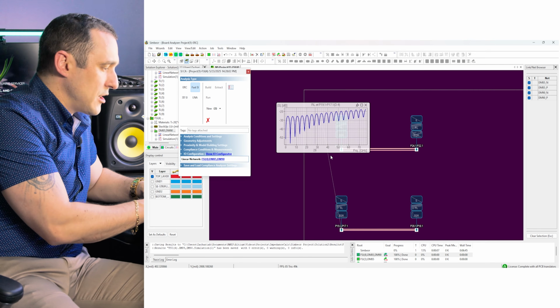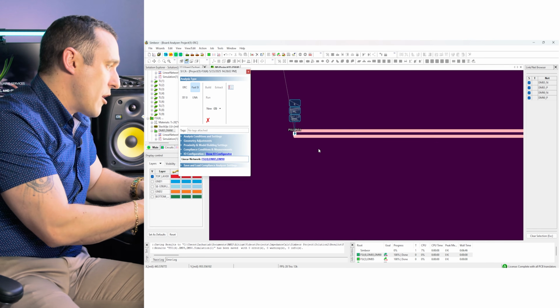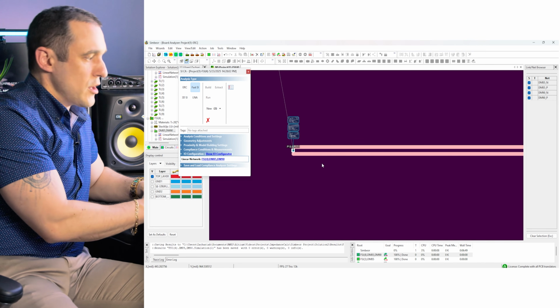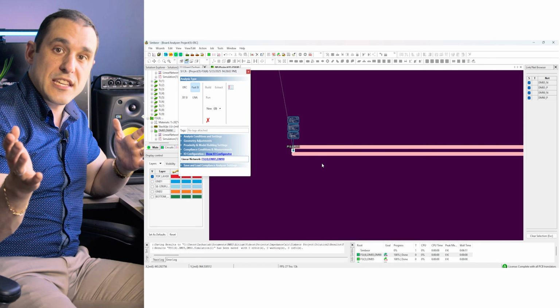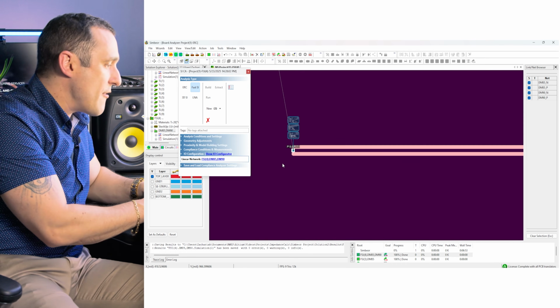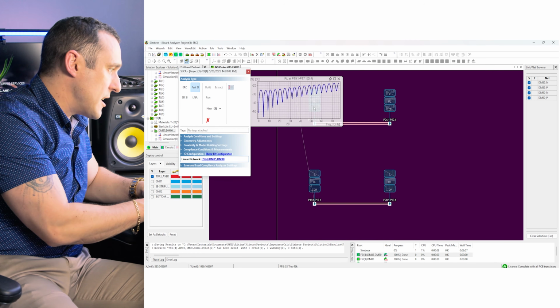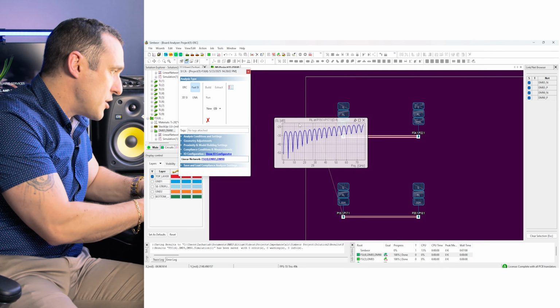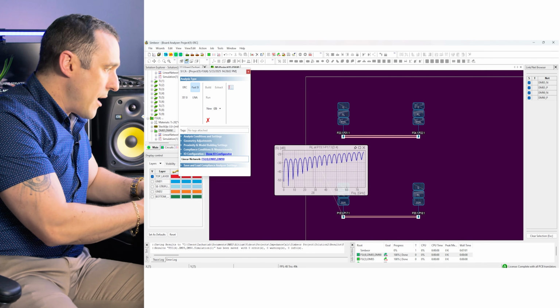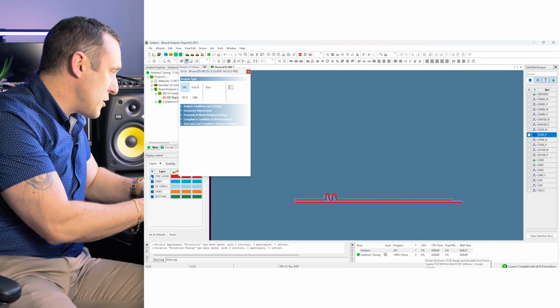So you can see here there's a little more return loss on this pair of microstrips. This pair of microstrips does have smaller spacing between the traces. So this one is at 5 mil spacing, and then these ones are at 10 mil spacing. So you can get a good comparison here just from these measurements. So now what happens when we have the length tuning sections?